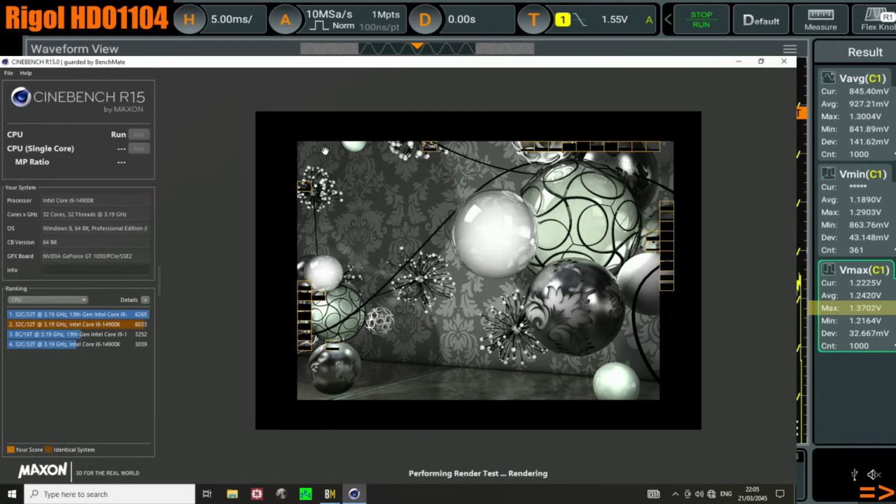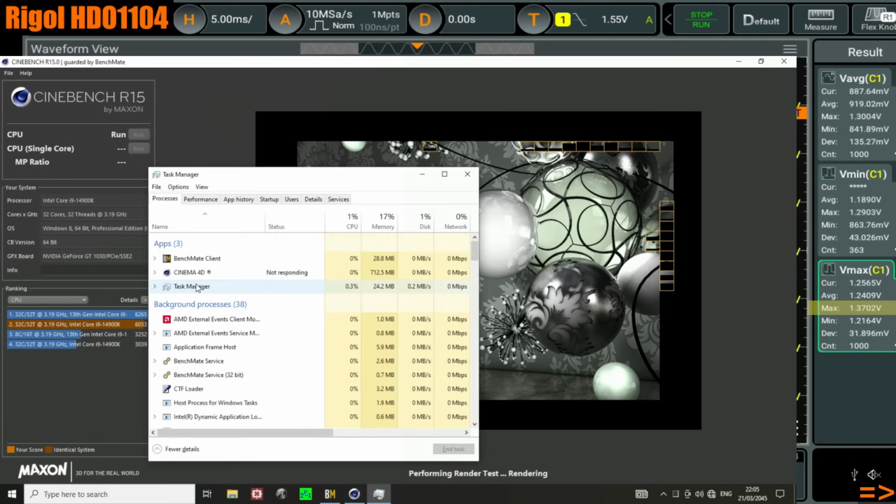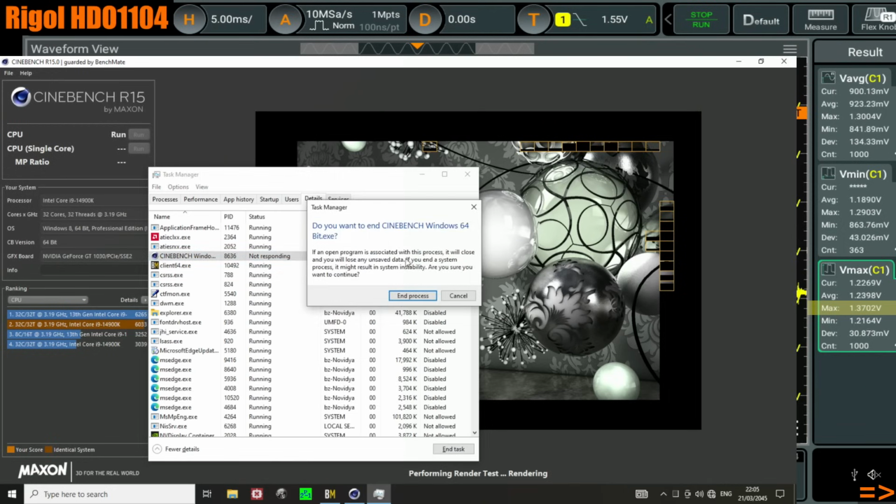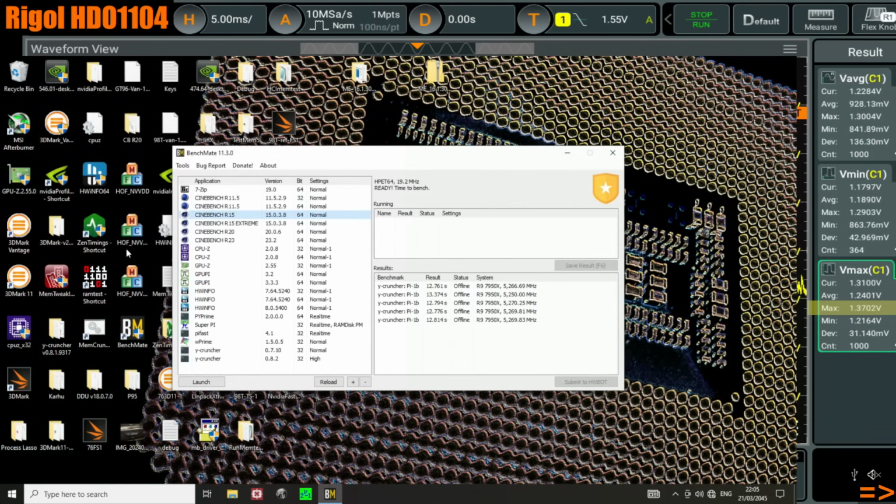And this is why, because they don't actually want to go and test every possible load scenario. Here I'm showing that Cinebench 15 is upset about this undervolt, but for all I know, the minus 100 millivolt undervolt could have been unstable in some application that I just don't know about, that isn't on this computer yet. Then one day you download a new app and you're like, oh man, garbage software, it's crashing, and it's actually your undervolt causing it, because that app uses a sequence of instructions that you never tested.